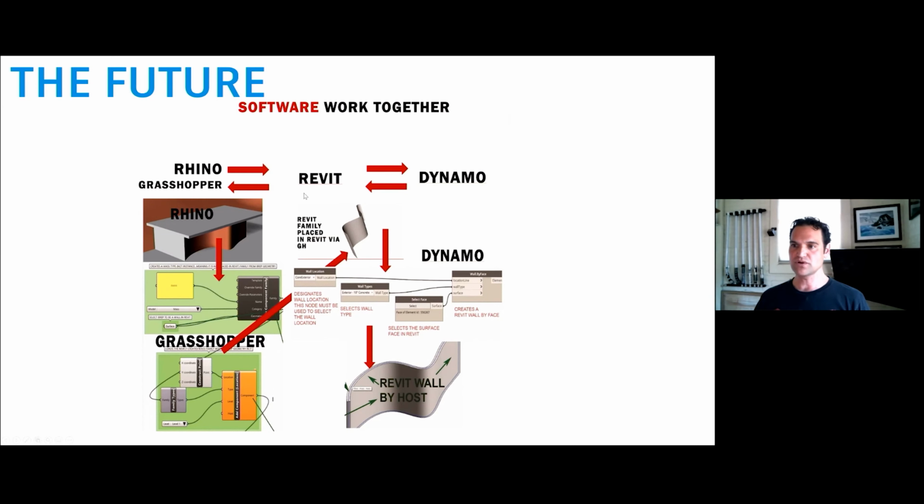So the way it works typically is what we talked about before, Revit and Dynamo working together. We showed examples of how to change to uppercase and build specific elements. If you have Rhinoceros elements that need to get into Revit, then what you can do is take your Rhinoceros geometry and use Grasshopper and then get it into Revit. Once it's in Revit, you can let Dynamo pick it up and do all the parameter changes and documentation and things like that. So they definitely can work together.